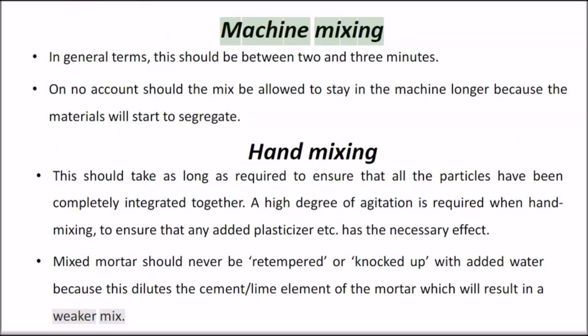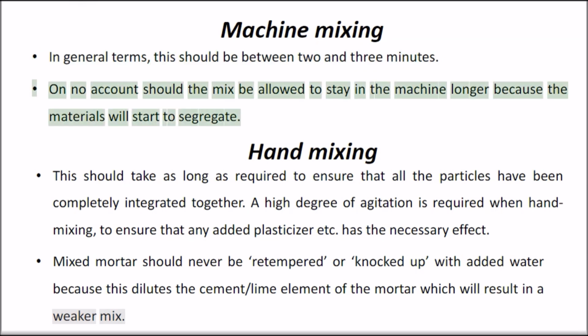Machine mixing. In general terms, this should be between 2 and 3 minutes. On no account should the mix be allowed to stay in the machine longer, because the materials will start to segregate.